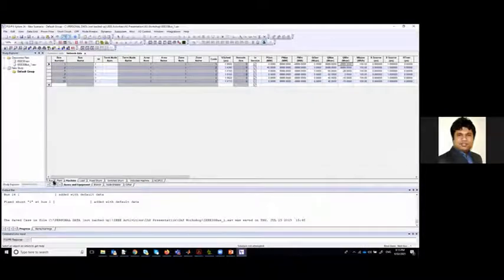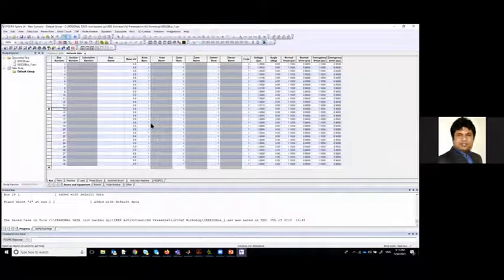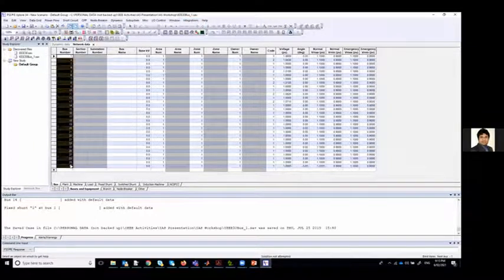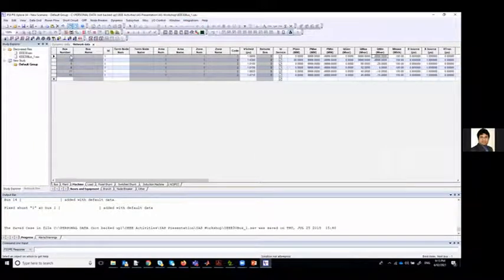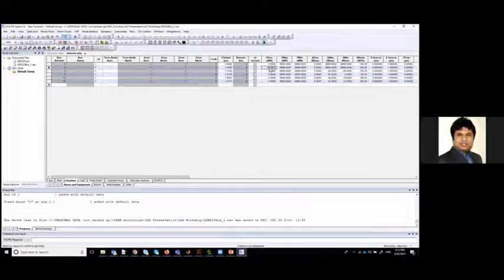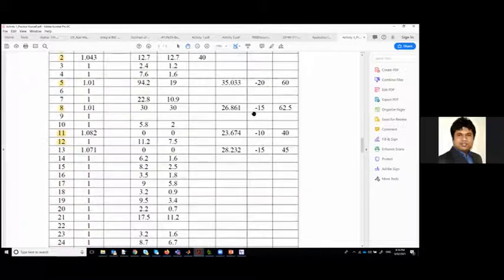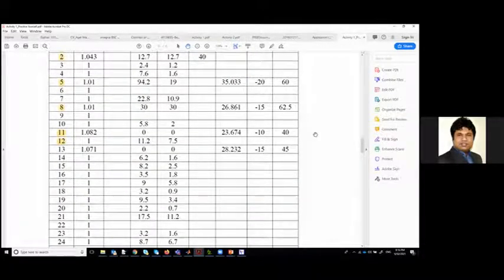So if you look here, this is the 30 bus. I'm showing you the 30 bus model that I have already developed. Okay, this is the 30 bus, all 30 buses I put in. If you look at the machine tab: 1, 2, 5, 8, 11, 13. And for the generator, I only put 40 megawatt. But for QGen, I did not put any QGen. For the others, I just put the maximum and minimum limits of the reactive power as provided here.